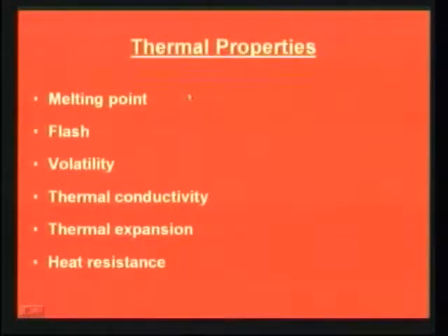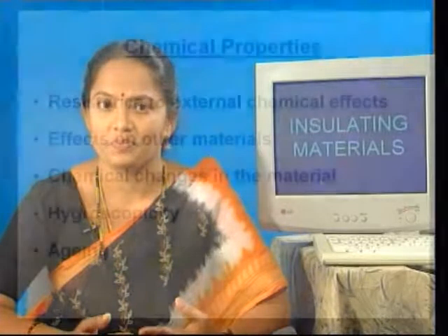The next factor is heat resistance. The insulating material used must be able to withstand the heat produced due to continuous operation and remain stable during the operation. This property is known as heat resisting property. It should at the same time not get damaged, or damage the other desired properties. Only then can current loading be increased, thereby making the apparatus capable of holding more power.